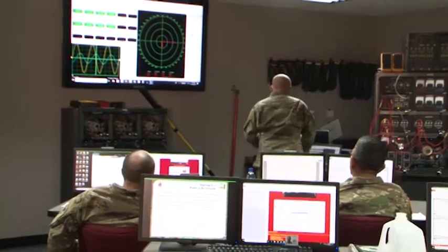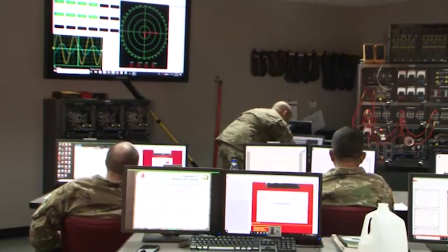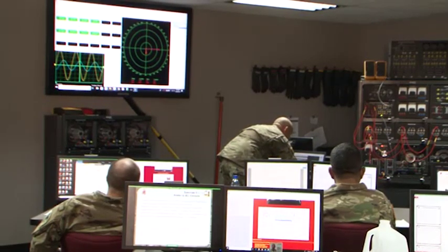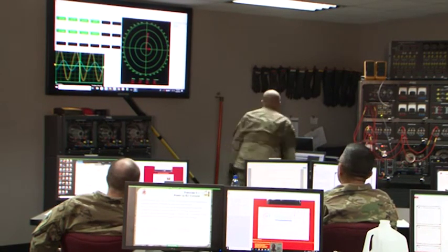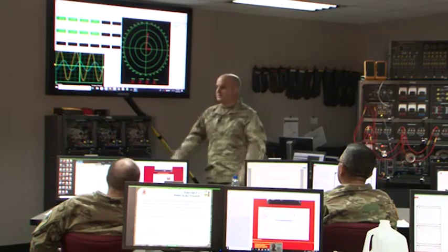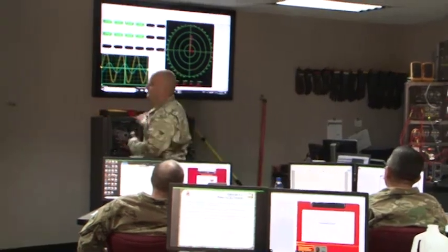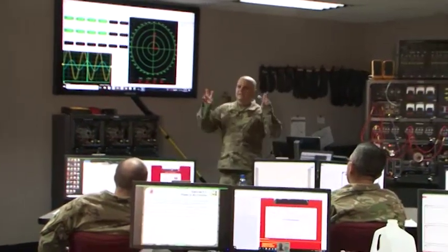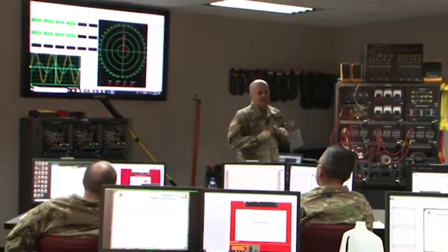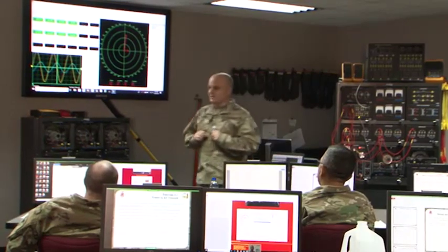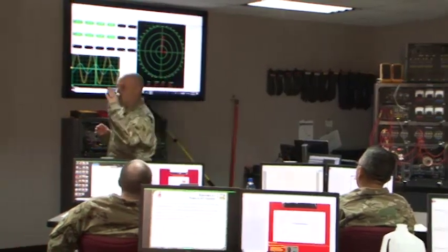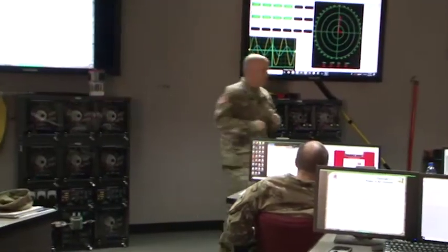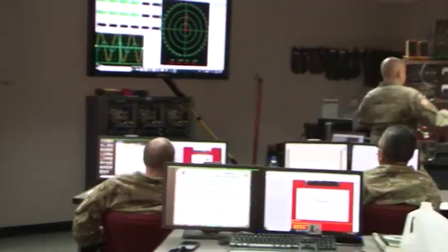All right, now what if I go over to my phasor diagram here, and up here at the top, I can set what my reference is. Now I'm going to set current as the reference. This goes back to what we talked about yesterday, right? Is there a difference in the relationship? No. It's still leading by 90, right? All I'm doing is switching what my reference vector is, correct? That 90-degree relationship and which one is leading versus lagging is consistent, correct? Okay. All right, so we demonstrated that.